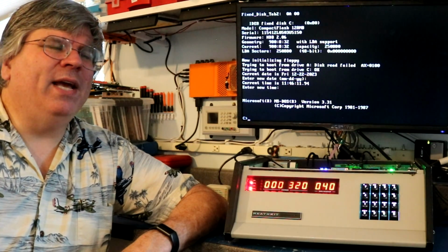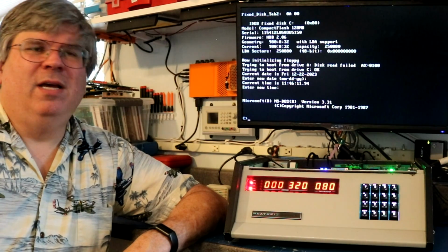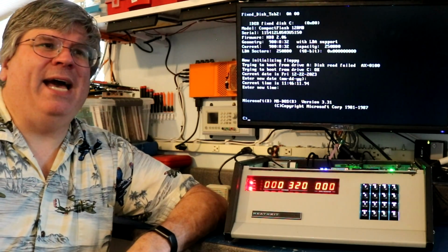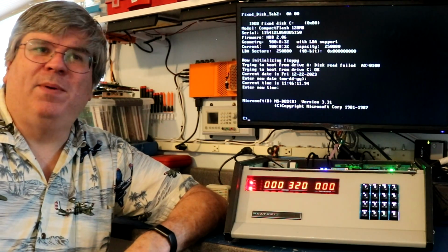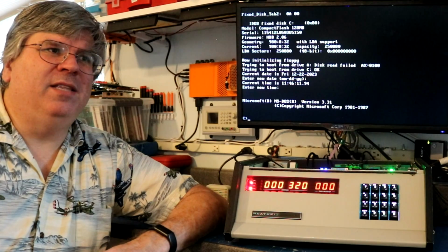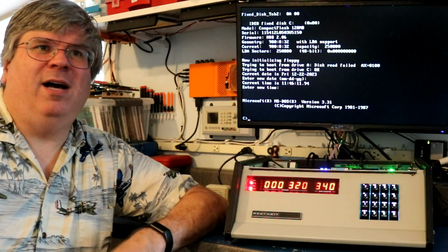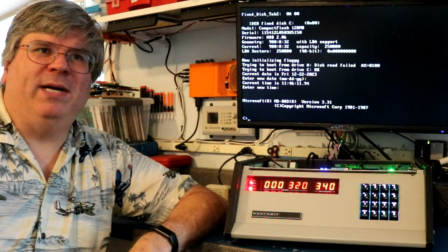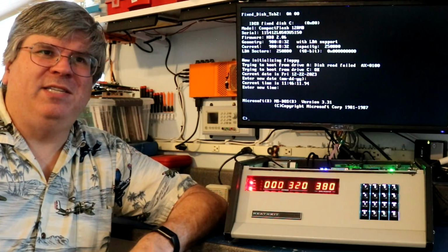And what makes the 8186 different is it has a set of onboard peripherals. Those include a variety of things that you would have had to add to a traditional x86 CPU to make an IBM type computer. Things like the interrupt controller, the DMA controller, the programmable timer generator, I/O addressing logic. All of those things are built into the 8186.